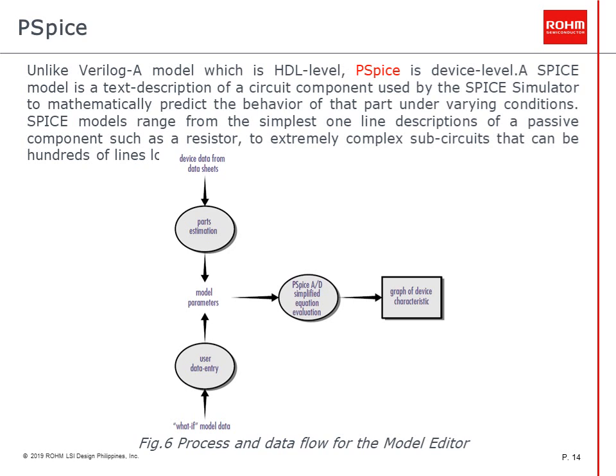PSpice AD supports analog and digital behavioral modeling, so you can describe functional blocks of circuitry using mathematical expressions and functions. PSpice simulates analog-only, mixed analog-digital, and digital-only circuits. PSpice analog and digital algorithms are built into the same program so that mixed analog-digital circuits can be simulated with tightly coupled feedback loops between the analog and digital sections without any performance degradation.